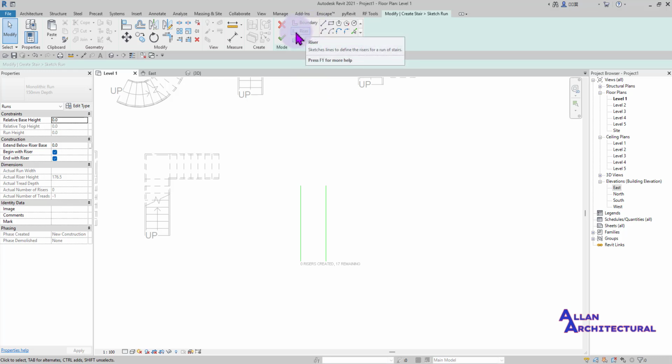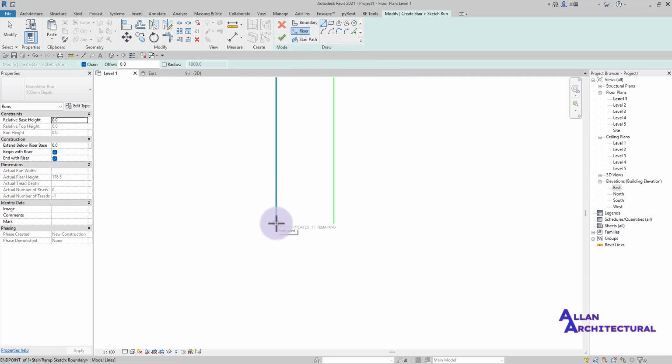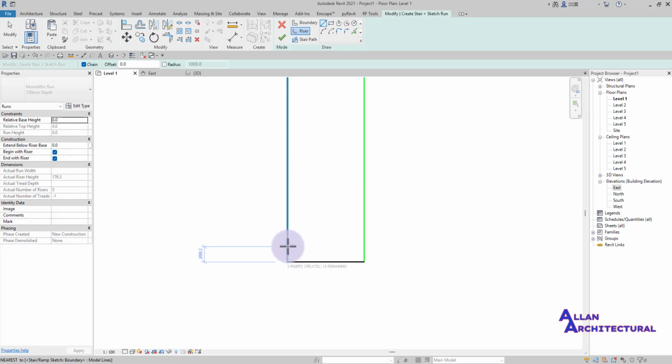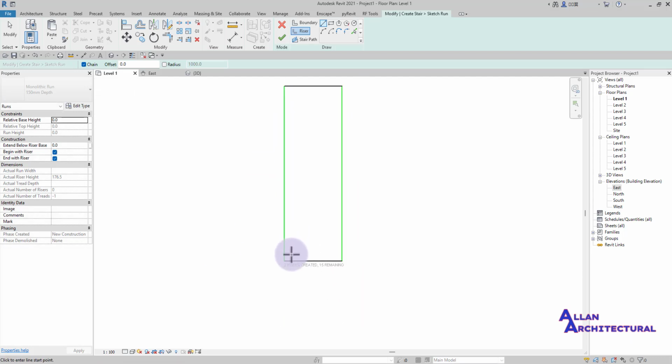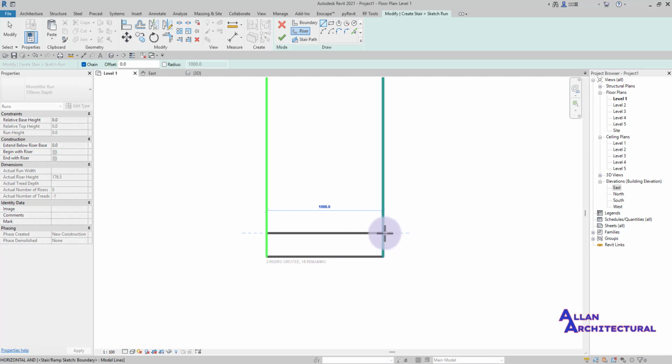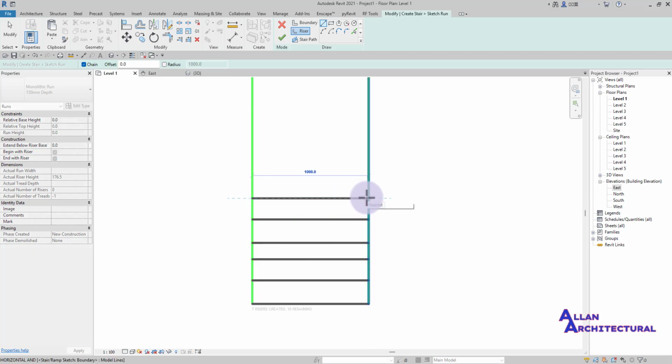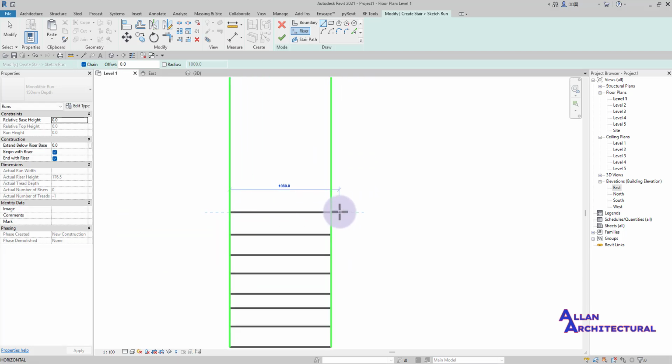So now the next thing we need to create is our risers. All right, so we can click on that riser in there, and then we start off by creating our risers. So you can click in there and then create those risers in there. Let me just make sure I create the first and the last riser in there, and then you can just divide that in there. So you can just divide, just create those risers in between in there. So you can just click on that, create all those risers in there. Now you notice my risers are not going to be equal in terms of width with the spaces in between here. I'm sure the space in here is going to be different than this and this. So I'm going to show you guys how you can actually make sure all those are all even in there.